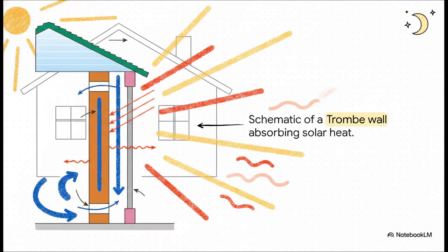Let's bring things back down to earth for a minute, to the absolute oldest, simplest method out there, just designing smart. Passive solar requires no mechanical pumps, no high-tech electrical circuits. It relies entirely on architectural engineering. A really brilliant example of this is the Trombe wall, named after a French professor, Félix Trombe. It's usually a very thick, dark-painted masonry wall built on the south-facing side of a building, with a layer of glass mounted just on the outside.